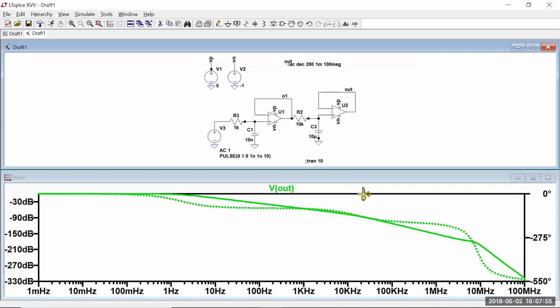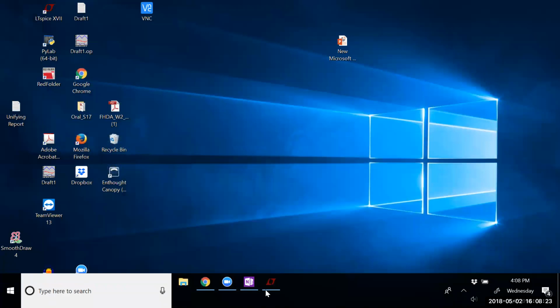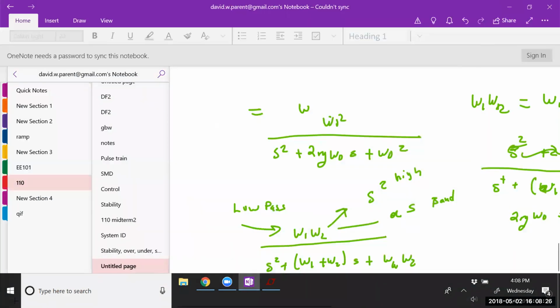And you might have, when you're debugging a problem, hey, this should be a second order filter and it's not working. Or, you know, my RC filter with op amp should give me minus 90 degrees of phase. So I should be able to add another almost minus 90 in a feedback loop before it starts to oscillate on me. But then all of a sudden it isn't. No, it's oscillating right there.